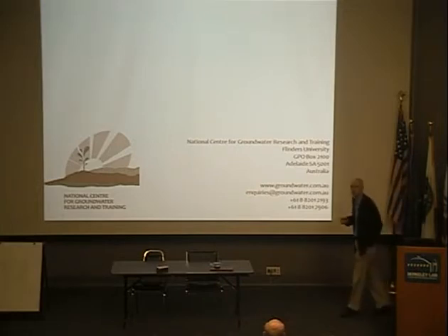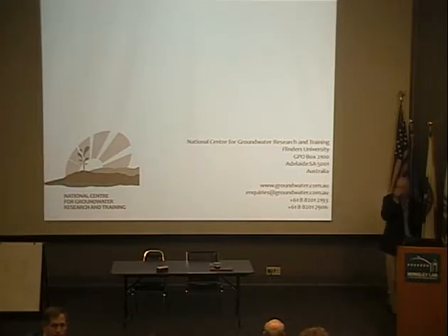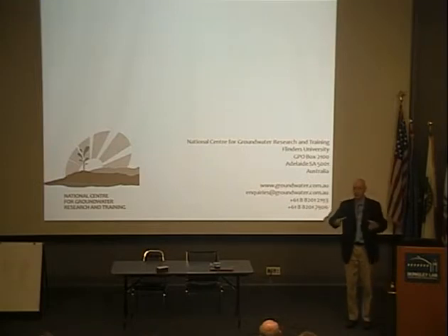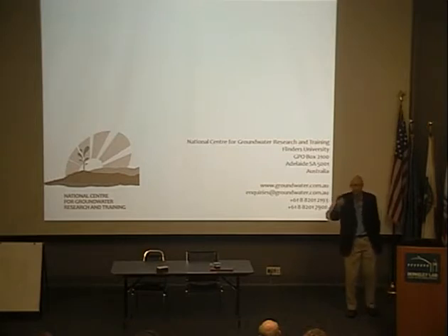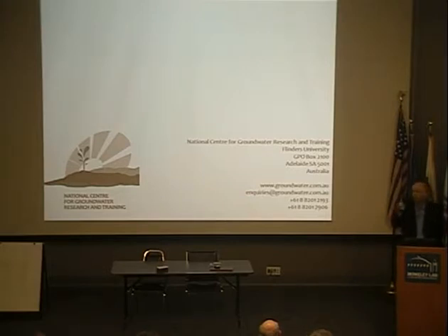You mentioned complications from the hyporheic zone, and maybe I missed it, but I didn't really hear you elaborate on how you try to account for the exchanges that are going on in the hyporheic zone. Yeah, the complications are particularly with instruments such as seepage meters that would record the movement in and out of the hyporheic zone, as well as the small net flux. And there are issues when people are using temperature to measure the stream, that water moving in and out of the hyporheic zone will also change the temperature signal. So each of these methods has complications.